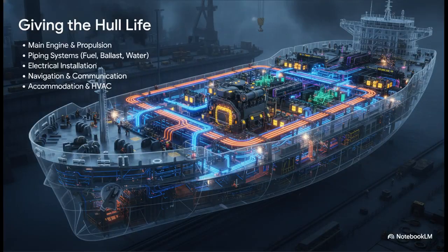Right, so a hull on its own is really just a big, empty steel shell. Outfitting is what brings it to life, and man, is this phase labor-intensive. We're talking about installing kilometers, literally kilometers, of pipes and electrical cables. The main engine, this massive beast, gets carefully lowered in, all the navigation gear, the safety systems, the living quarters, everything gets fitted. It's seriously like building an entire industrial city, all contained within that steel frame.